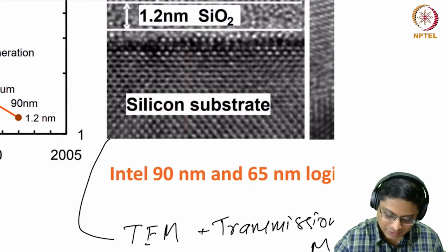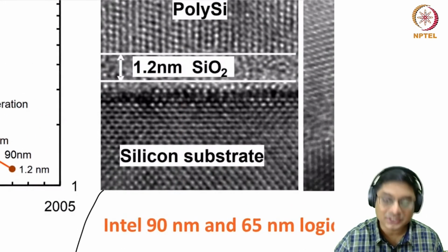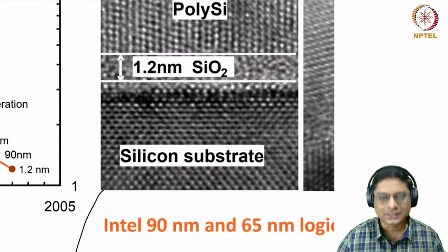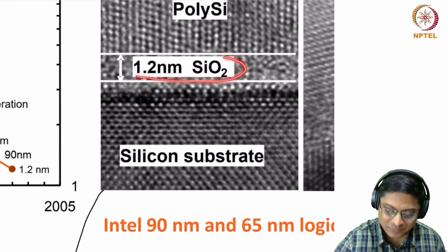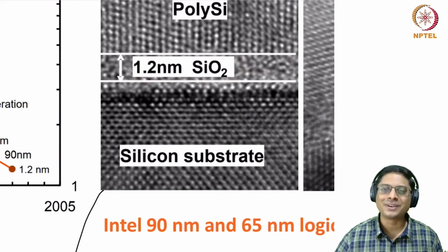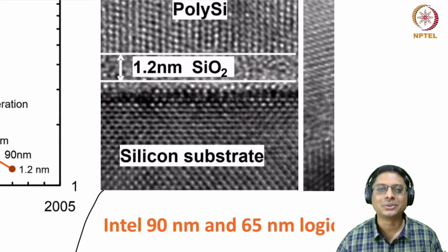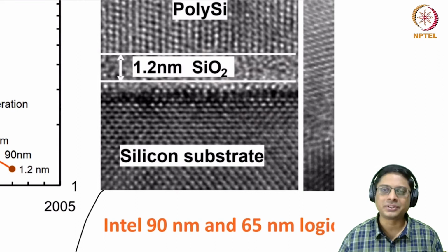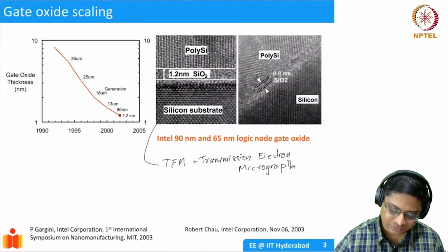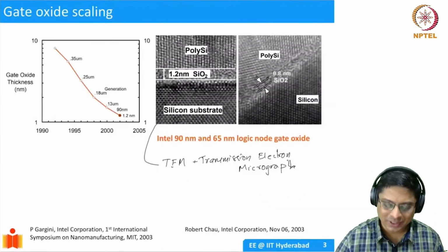On top of it, you see this is the oxide, which is an amorphous material. So you don't see that orientation, right? You don't see this perfect lattice arrangement of silicon. You see some random silicon and oxygen atoms. And the thickness is just 1.2 nanometers. You might wonder, how did we take this image, right? If you want to take this image, there's an equipment called TEM, which costs a few tens of maybe up to $10 million or so. It's a very, very expensive equipment. With that, you can take this image. And then, so you have the silicon substrate and 1.2 nanometer oxide.